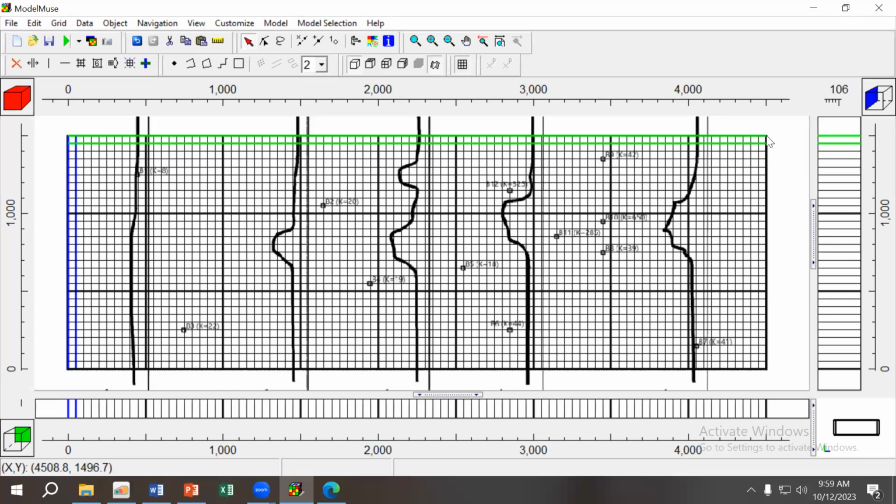Do you understand the problem? Yes or no? I understand the problem, it's just how to apply it here is a little. No, not how to apply it here, how to solve it in general. I'll show you how to apply it. The only way to solve this problem is that your last column of cells, you just subdivide it. Instead of making it 50 by 50, you make it 50 by 10. So if you subdivide it, make it 50 by 10, then now I can say 10 interval here, 10 interval here, 10 interval here. So that's what we're going to do. The problem is, I want to have a river that sits on top of these cells here.